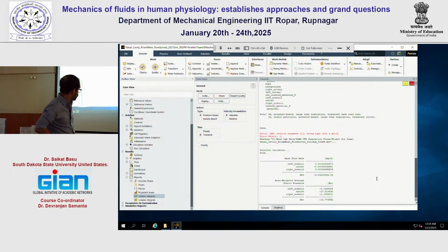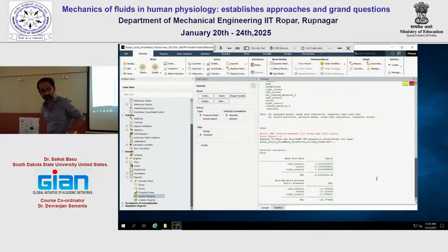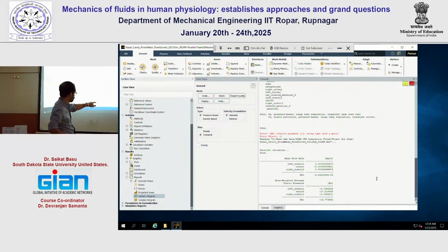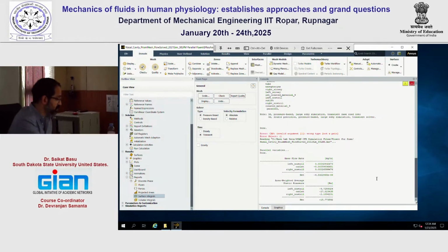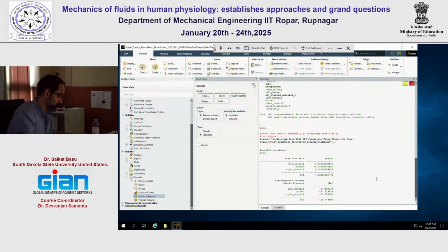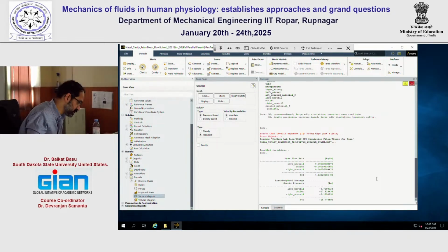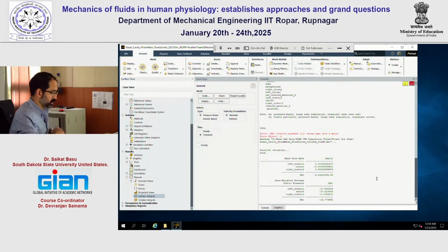Now, we also have to report the delta P. To report the delta P, what I do is I take this absolute pressure at the outlet and figure out the mean of the other two, and then subtract that from here. So let me go to your printed pages, and there is an example of this, but it's a different simulation, the one that I have included in the printed pages.